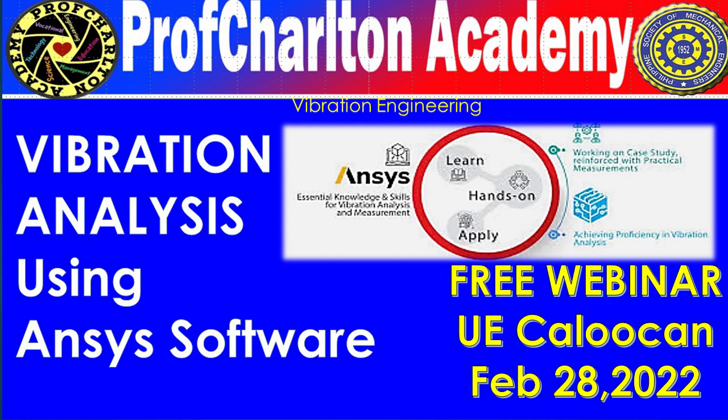Now, let's say you also want to see the stresses. You can insert one more result: solution, insert. You can see here we have a lot of results: deformation, strain, stress, contact results, reaction force. Let me insert stress.